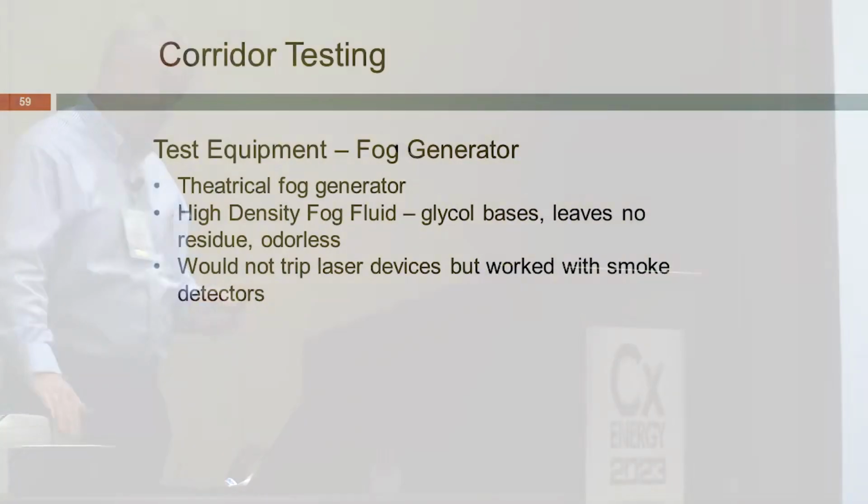Smoke detectors were initially covered. The exit sign line of sight visibility was established to the AHJ and DOR satisfaction. Smoke detectors were then uncovered. Two detectors were needed to initiate an alarm per zone. Line of sight restoration was timed. Airflow patterns and currents observed. Initiation was always allowed to be via automatic. We weren't ever manually tripping.